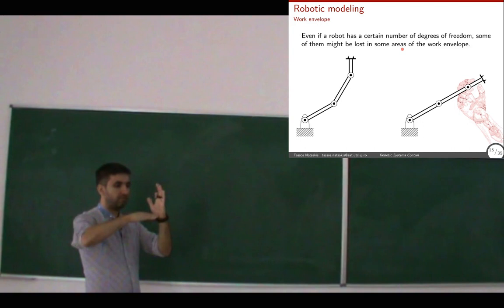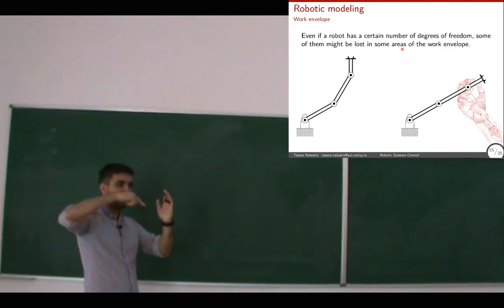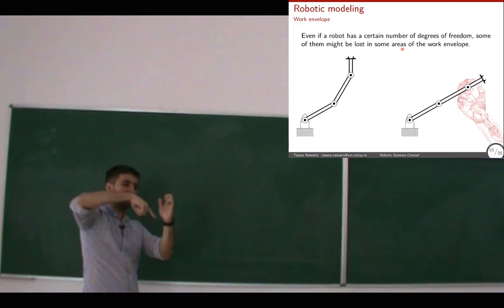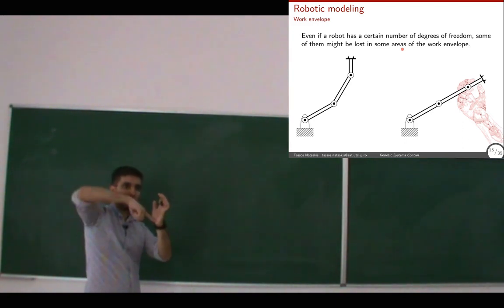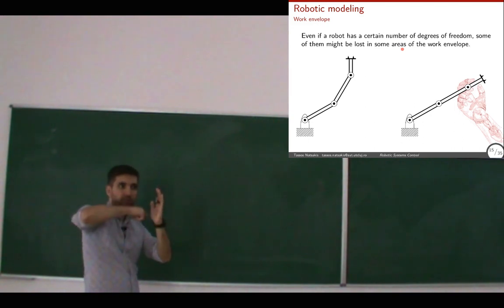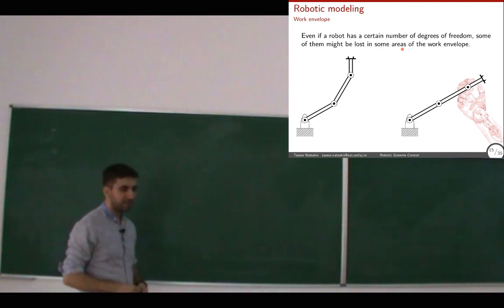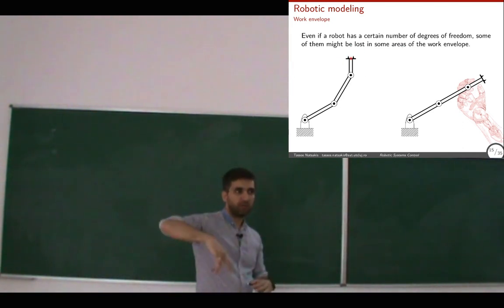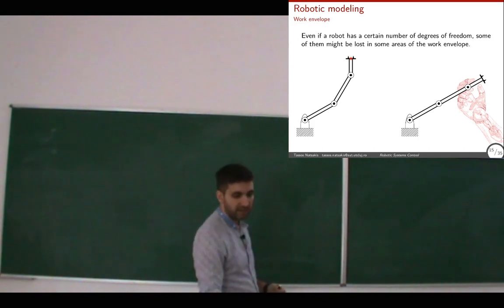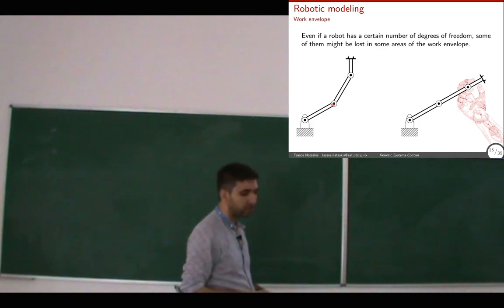It's a technique for gluing together metal pieces, and we have a tool. I need to control the position and the orientation of that tool so that it does the welding properly over time, okay? So I usually care about what happens at the tip of the robot. Of course, when we want to avoid obstacles and other more weird cases, I care about what's happening also between the tip and the base of the robot. But for now, we're going to stick to the tip of the robot.